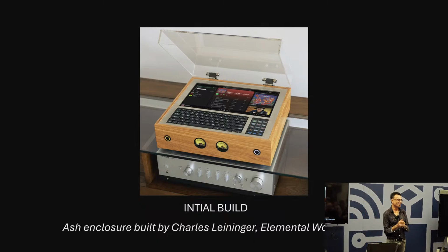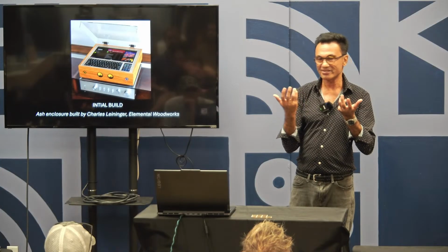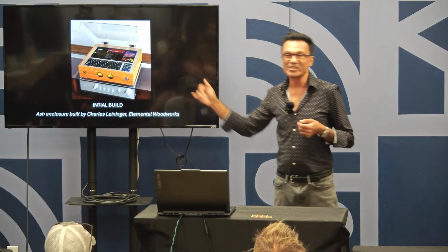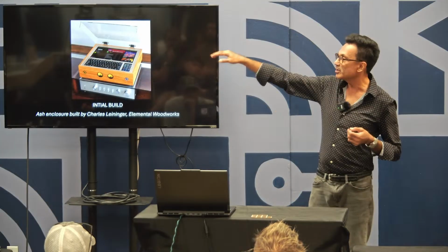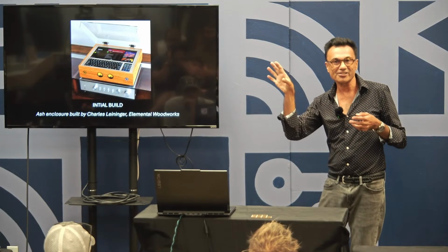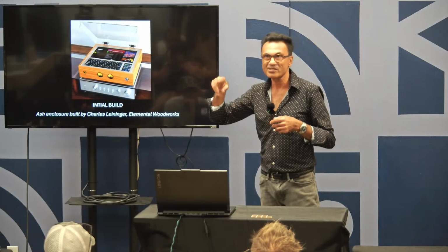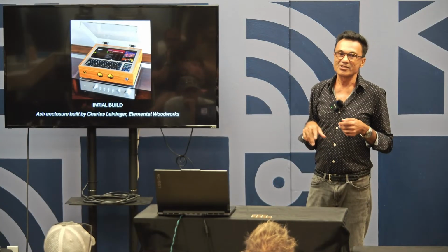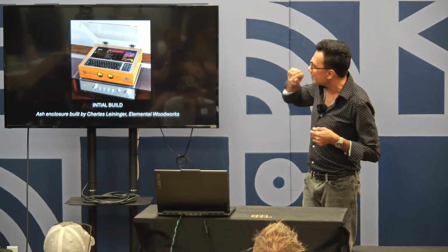No surprise there, right? So one of the things I realized, it gets really hot in there. Most such components have ventilation slots on the top, obviously, because convection is how heat dissipation occurs. This does not. It doesn't have any holes on the sides either. I'd put slots in the back, thinking convection, and the base plate has a lot of slots on it, thinking that would be good enough. No, it wasn't good enough. So the next version, I had to put fans in there.